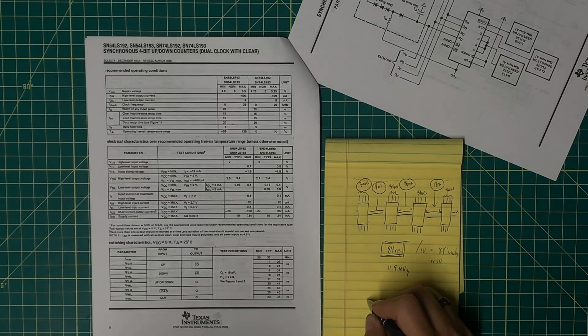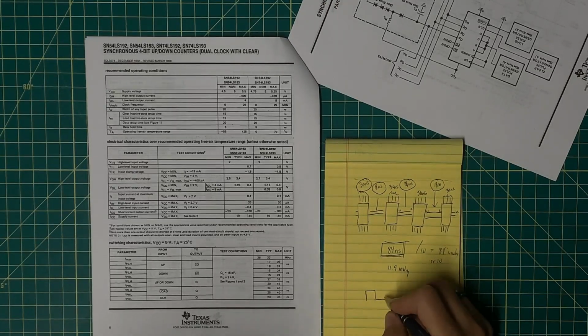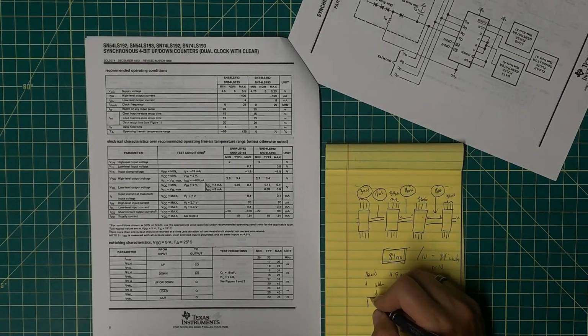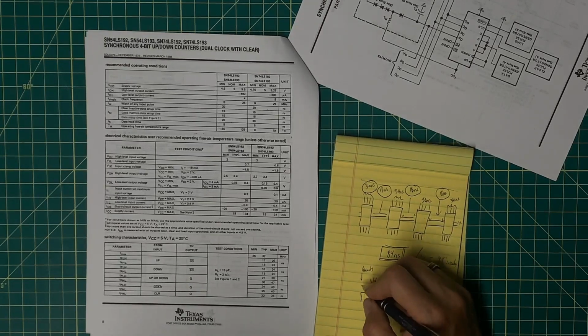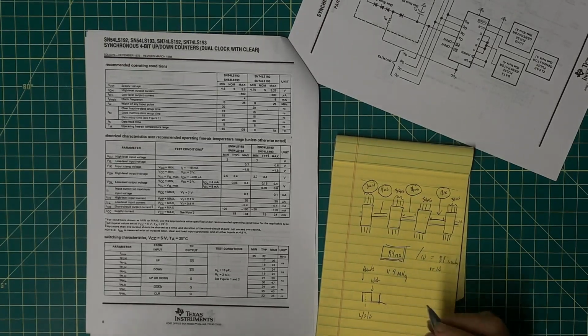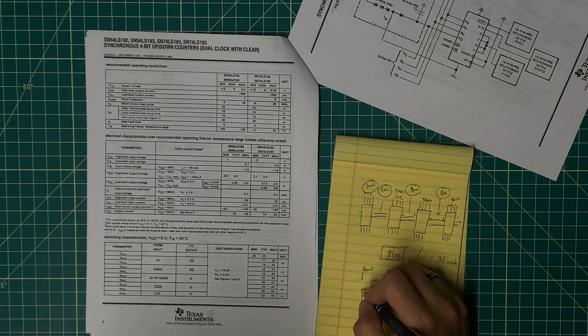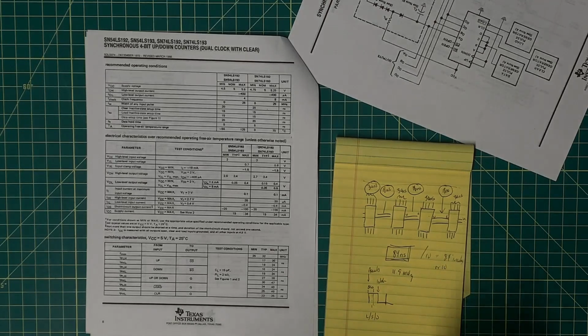But if I look at that, here is my latch, here is my asserts, and at some point in here is my load increment decrement. I've drawn it offset, but perhaps that's in the middle of this clock cycle. Then the time difference between here and here has to be 84 nanoseconds for the LS logic.